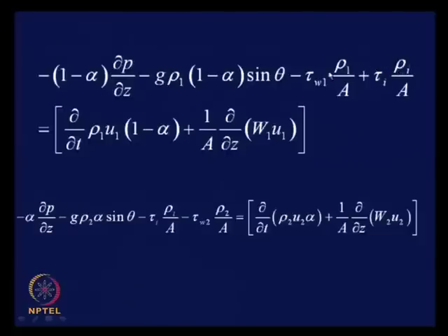There are certain mistakes which I mentioned in the last class. These are going to be S1, S2, okay, the interfacial and the. So, these are some typographical errors, we will be correcting them. So, we have a tau I here and we have a tau I here also. Now, remember one thing, we are considering the separated flow model which interacts at the interface, but there is no mass transfer between them and there is no phase change between them.